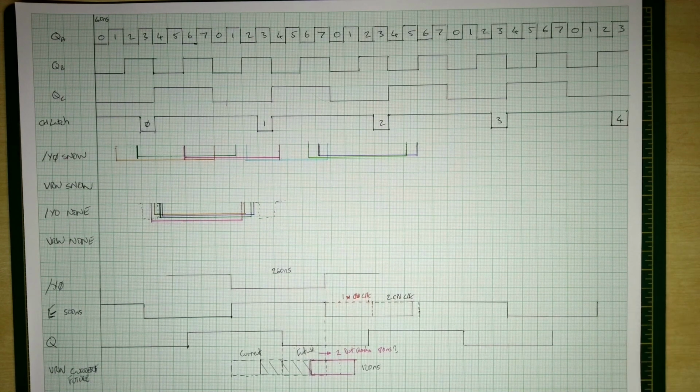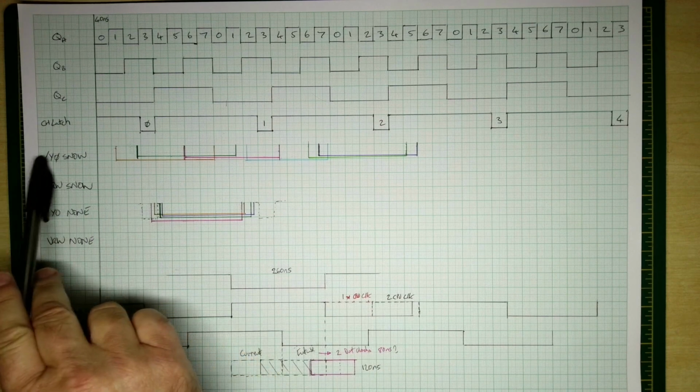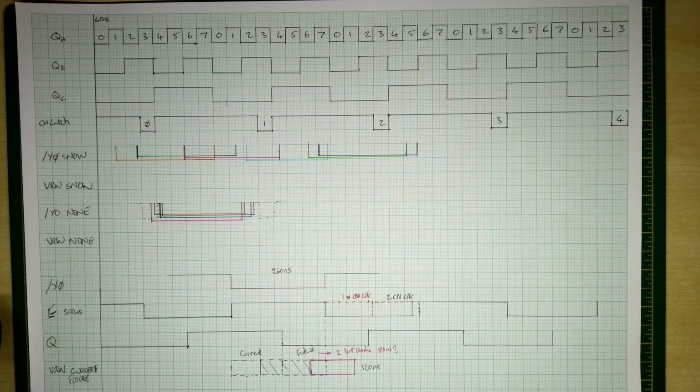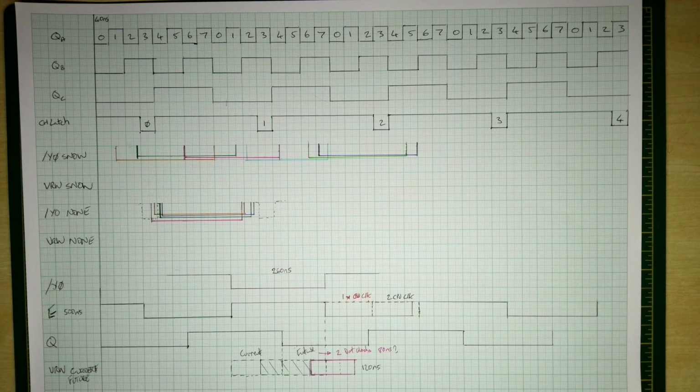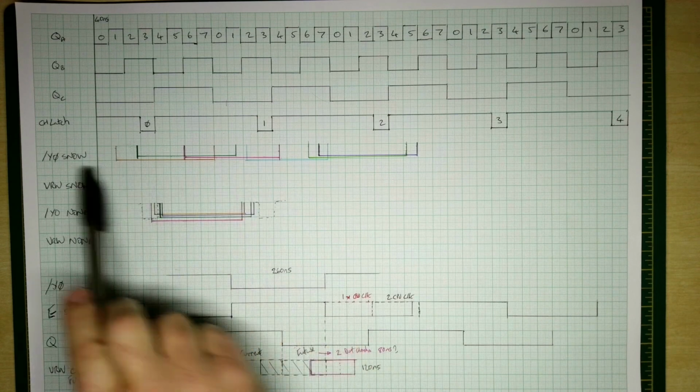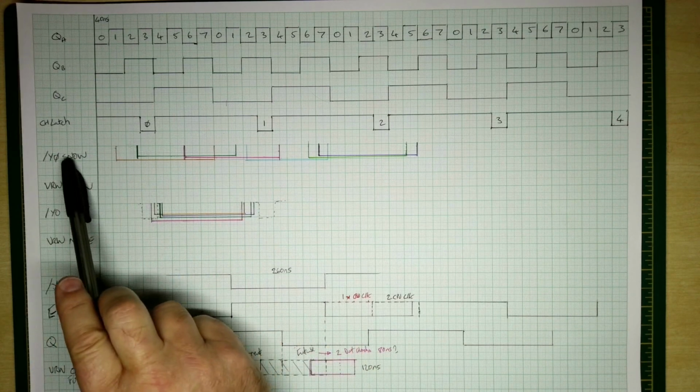And what I did for a variety of the samples was look at where the Y0 video RAM select and the VRW video read-write select were overlapping. Now in fact, as I went into it, it's more down to the RAM select, because we're both reading and writing to the RAM in some cases. And what I did is I plotted out the instances where the snow was actually occurring.